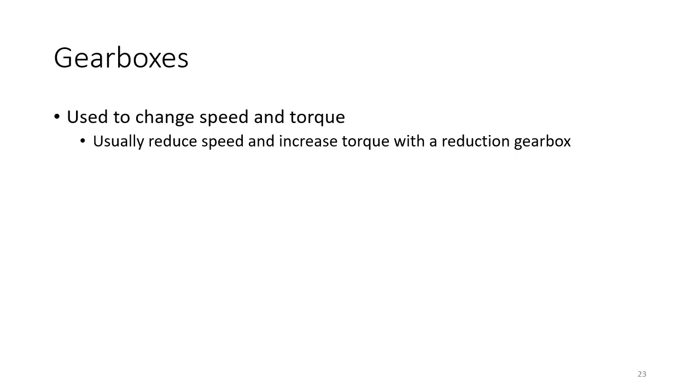Sometimes it's not quite as straightforward as that. There might be a few losses in the gearbox, but normally they're minor. So generally, it's a straightforward ratio of reduction in speed and increasing the torque. You can do it the other way, but that's rare. You can use it to reduce the torque and increase the speed. But there are problems with doing that. First of all, you have to consider, can my device actually cope with the speed I require? If you're putting a high speed into an increased speed gearbox, potentially your output speed could be so high you could actually destroy the gearbox due to the mechanical forces. So reduction gearboxes tend to be a lot more common and also a lot more useful.